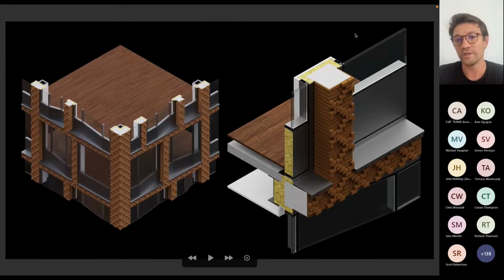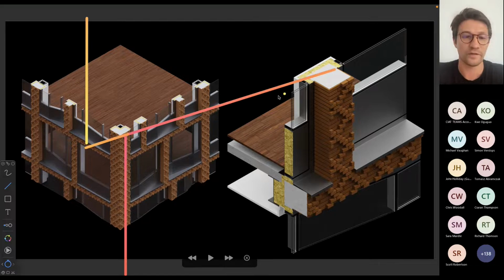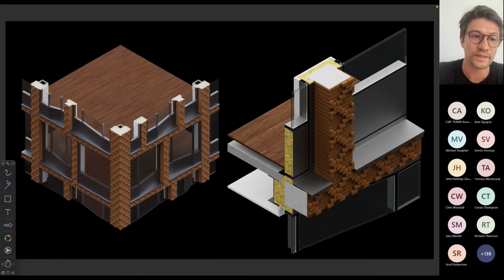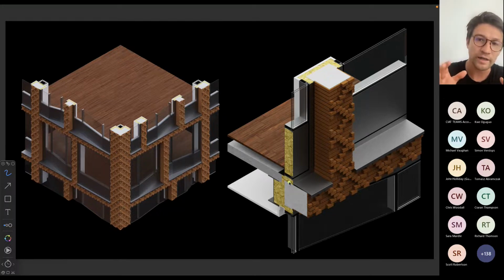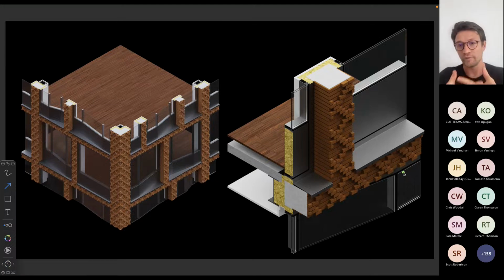In that case, what usually tends to happen is that the precast is installed separately to the windows. So the precast concrete elements get installed first, separately to the windows. That would not be the panel as we've seen in the previous element. It would not be split. This would be beams and columns that are purely decorative, and they are there just to receive the complex brick pattern with protrusions and recesses. So that's purely decorative, and they don't serve any other purpose.